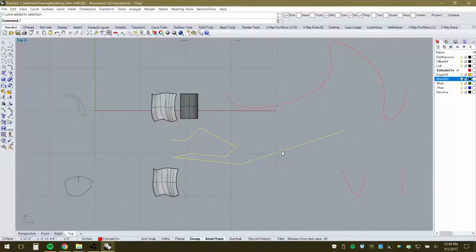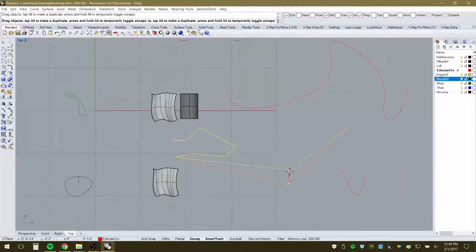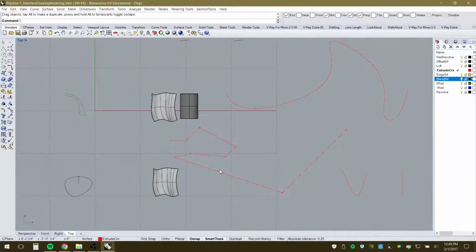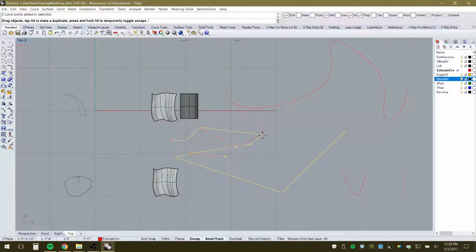That's a little bit different than this with the straight edges that I used this polyline tool for. Again, F10, so now if I select one of these, it's going to be pretty absolute. These are straight segments, and so the surrounding points are going to maintain their location, and it's just this one that'll change those particular vectors, and so the object snaps will respond accordingly. And again, I can select a couple of these, move those around in concert to one another.